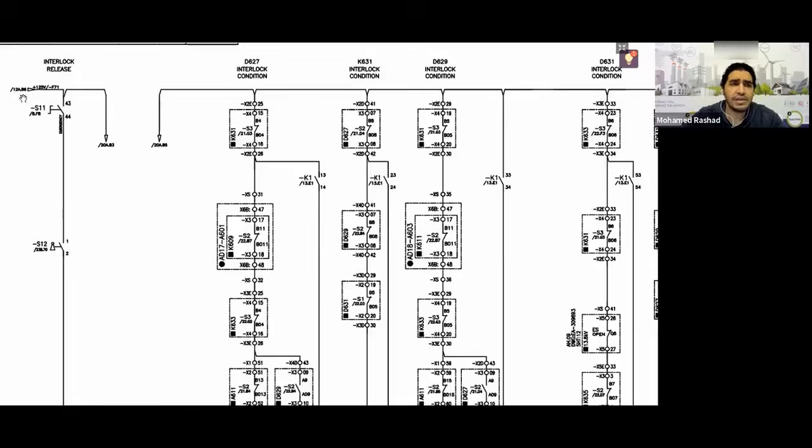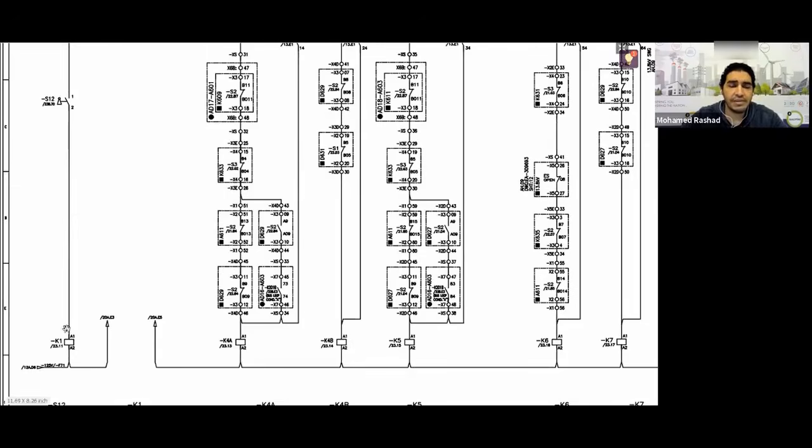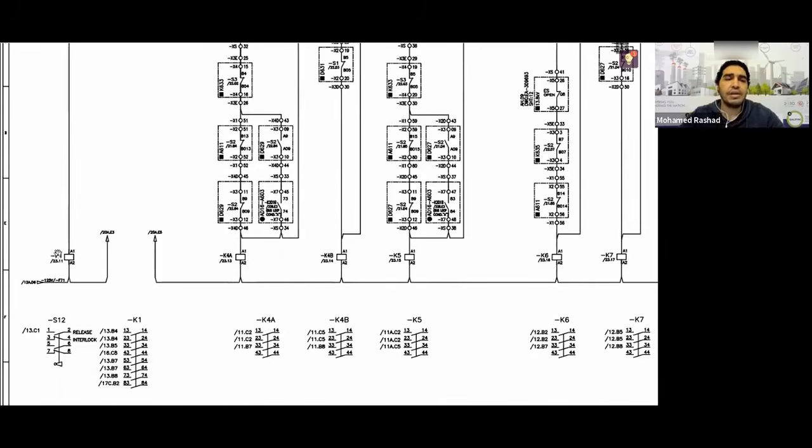The first thing I will find is that it shows me the positive and negative from below here. And here I have the auxiliary relay or the contactor, which is called key 1. Before it, I have the emergency position, which is a selector switch for the emergency position. And here I have a push button or a switch, you could call it, which is a self-return key. It's the type of switch where you turn it on, and if you release it, it will self-return, or go back to its normal position again. All right, great. This part is related to something we call interlock bypassing.